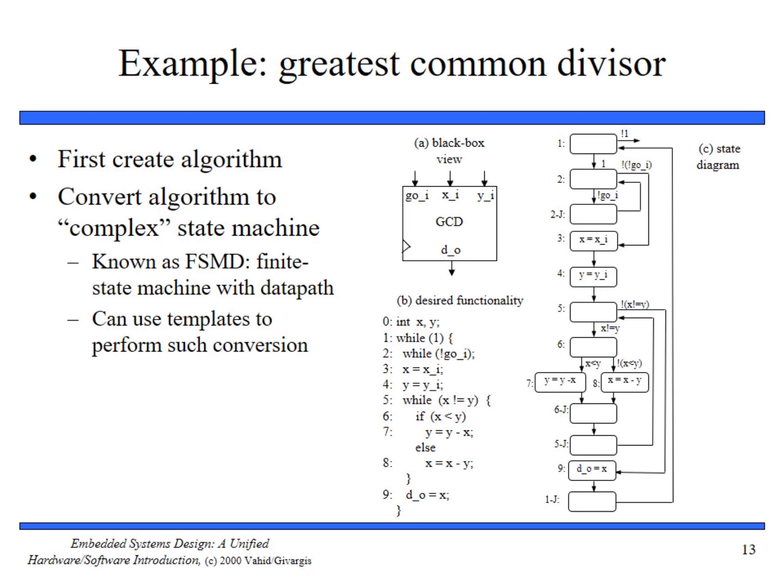Therefore we now describe the technique to convert computational tasks into a custom single purpose processor consisting of controller and data path. We begin with a sequential program describing the computational task that we wish to implement.